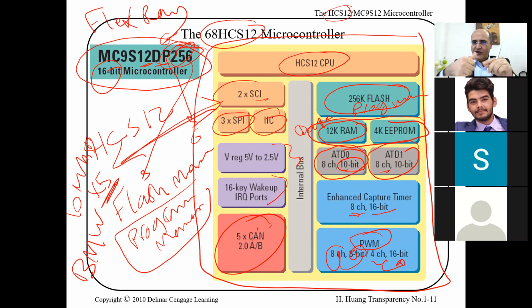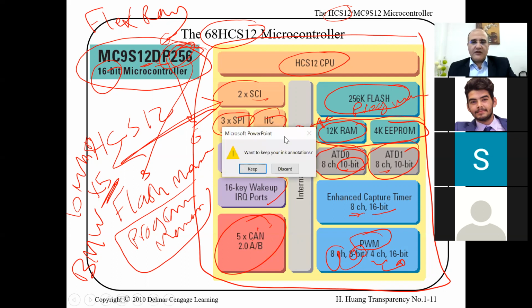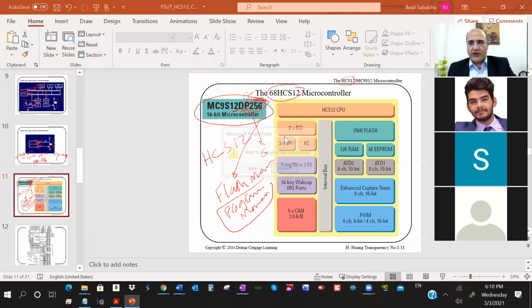He plugged into the OBD, where you have the 2 CAN bus lines, and made a microcontroller write a signal with the same ID as the brake message, wrote it at a faster pace, overwrote the original brake signal, and caused the brake to hit and the car to stop on the highway.